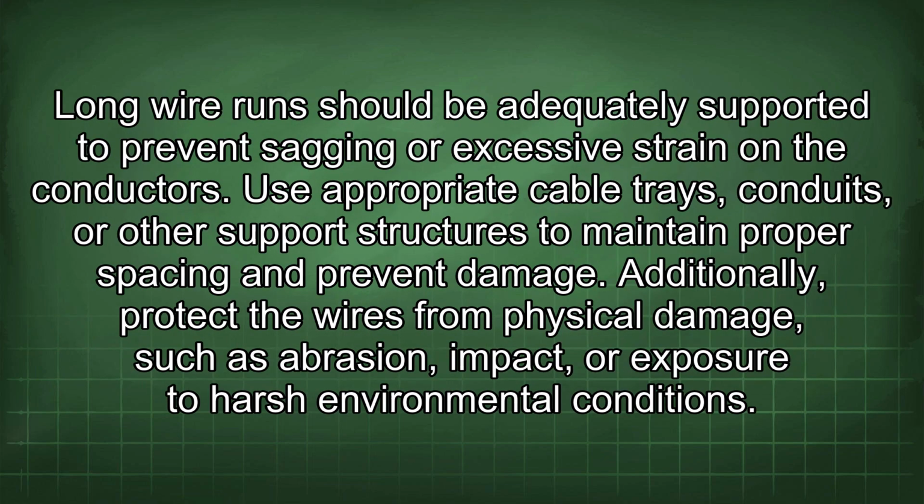Thirdly, consider the mechanical support and protection of the wires. Long wire runs should be adequately supported to prevent sagging or excessive strain on the conductors. Use appropriate cable trays, conduits, or other support structures to maintain proper spacing and prevent damage. Additionally, protect the wires from physical damage such as abrasion, impact, or exposure to harsh environmental conditions.